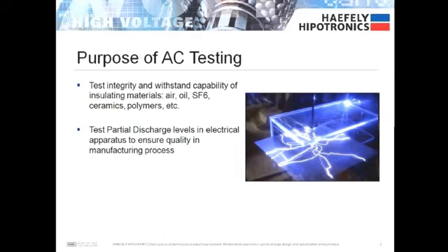Okay, so just as a refresher to most of you, I want to go over the purpose of AC testing. This is to test the integrity of the different insulations in all the electrical equipment that we deal with on a day-to-day basis, from air to oil to SF6 gases, anything that needs to act as an insulation in high voltage electronics.